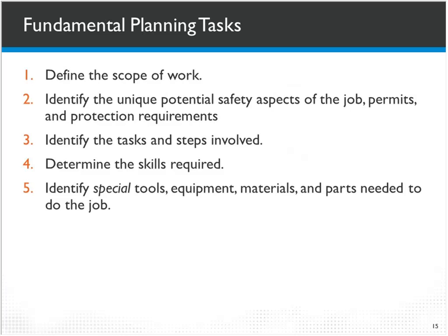One is the scope of work, to actually take time to go out on the floor and look at that work order or work request and vet it and talk to the people who wrote that work request and go and look at the scene yourself and see what's going to be involved and look for unique potential safety aspects of the job, like if scaffolding would be so high that it would impact overhead live wires, that would be important to know. Or if they're fixing a valve, well, do they need the valve replacement kit, or is it just as simple as just tightening up the packing, et cetera.